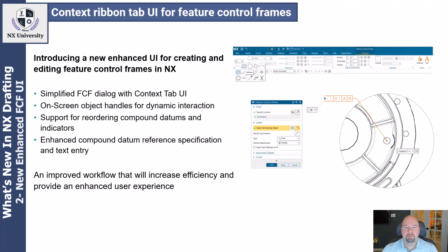This is going to allow for a simplified feature control frame dialog with that context tab and user interface. It does support reordering compound datums and indicators here, and it allows for an enhanced compound datum reference specification and text entry when you create these feature control frames. This allows for an improved workflow that's going to increase your efficiency and provide an enhanced user experience.